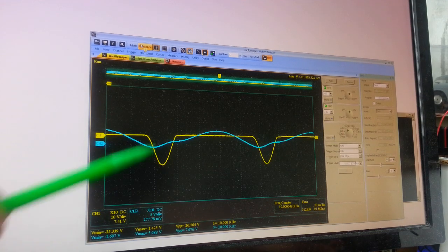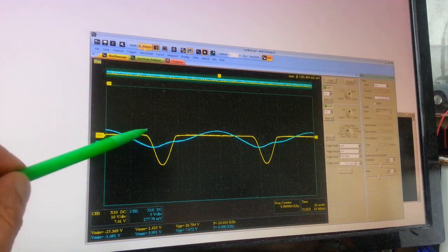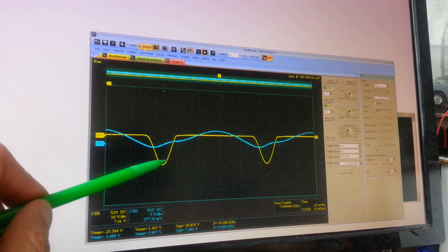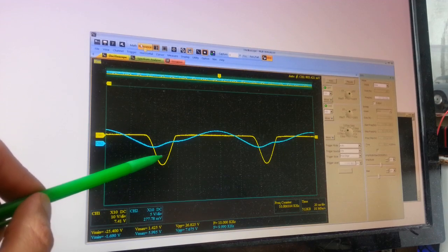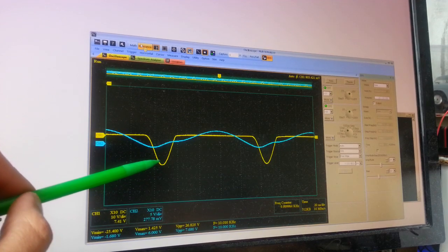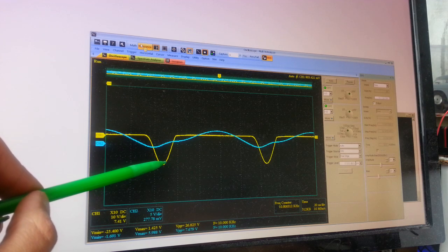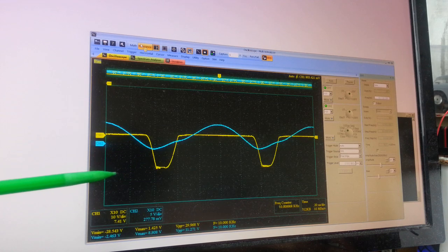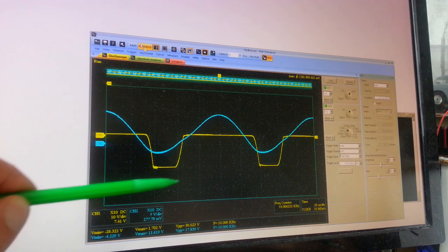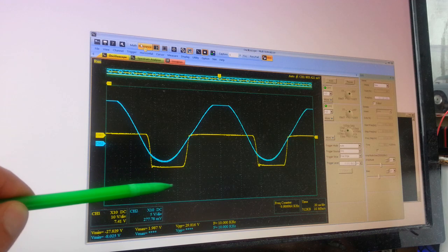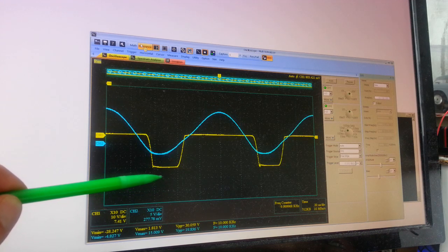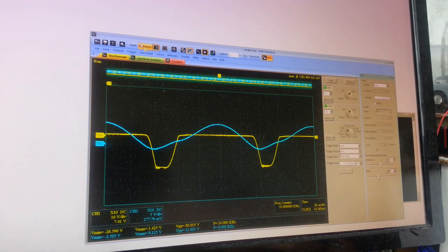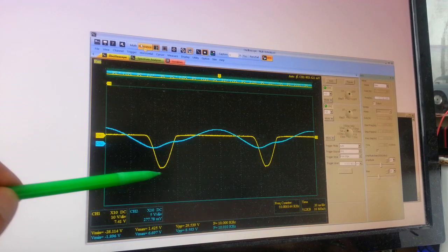When this voltage, which is basically the voltage across the closed diode, is increasing and becomes significant, we're going to see that the diode opens up and the line becomes flat. So let's see it once again. I increase the voltage up, and now I have the flat line, meaning that at this moment we have the breakthrough on the pn-junction.